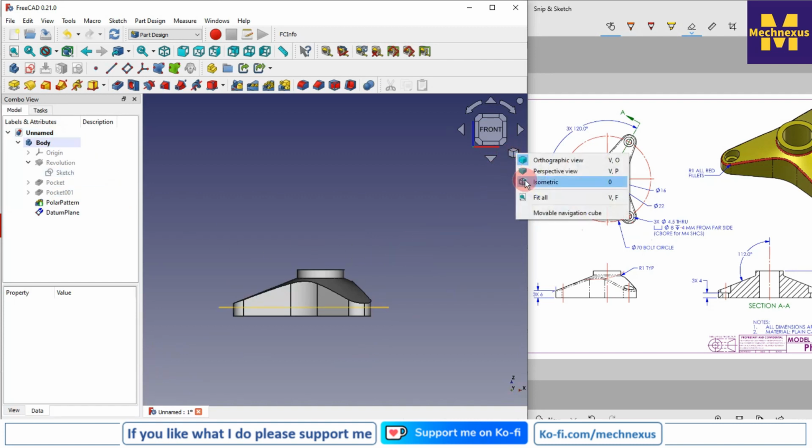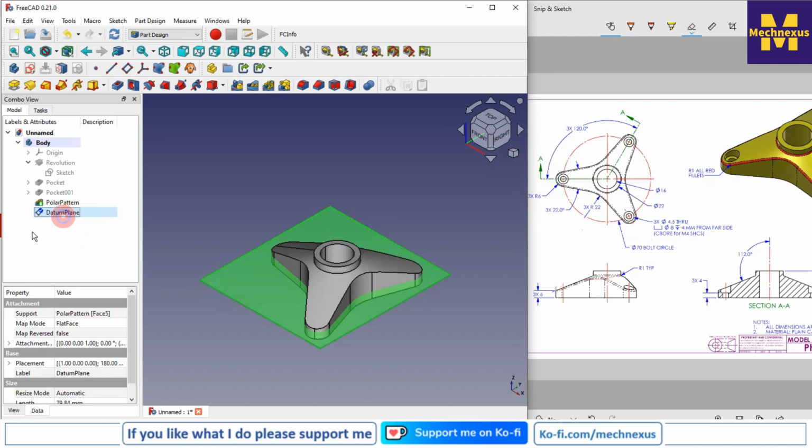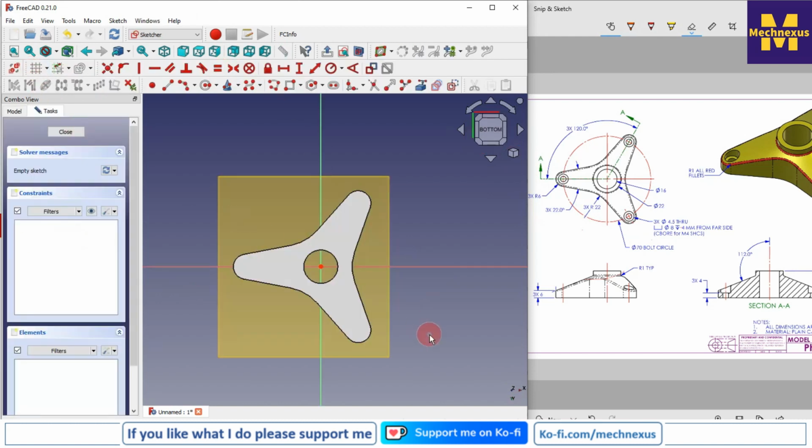Now I will switch to the isometric view, select this datum plane and create a sketch. And now this counter bore dimension is given. This is a 4.5 mm through and 8 mm, 4 mm from the far side, so it is 8 mm. So what I will do, I will click on convert geometry